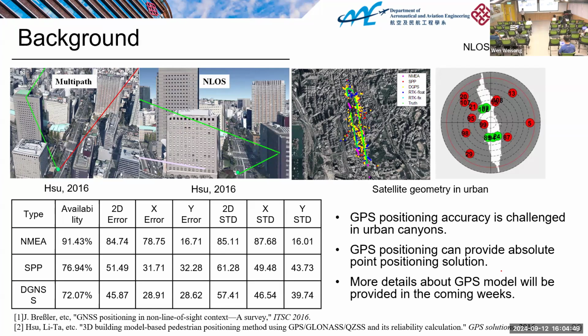Okay, so the errors using different GPS positioning methods. I mean the horizontal position error. Horizontal means 2D, two dimensions. The error can easily reach about 84 meters by GPS. 84 meters for GPS. And for example, if you use some differential, high level technique, it can improve, but this is still more than 20 or 40 meters. This is not acceptable for the auto-driving cars, right? So these are the big errors.